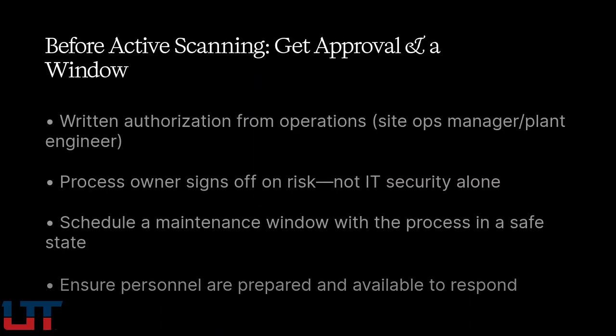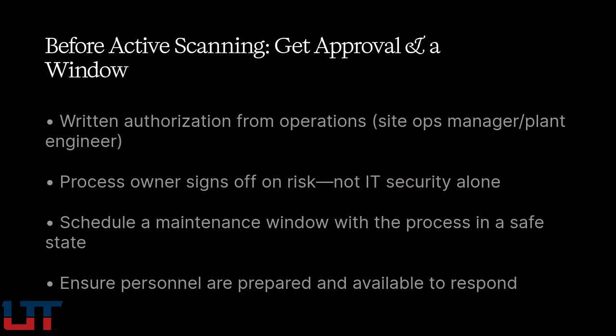If you determine that active scanning is necessary in your environment for a scheduled security assessment, a new equipment audit, or a specific diagnostic need, these requirements apply before you begin. Written authorization from the appropriate operations authority. In most OT facilities, this means the site operations manager or plant engineer, not IT security, not the OT security team alone. The person responsible for the process must sign off on the risk and the maintenance window.